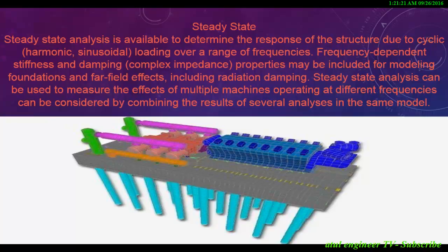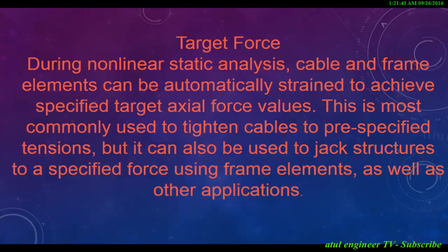Steady state. Steady state analysis is available to determine the response of the structure due to cyclic, harmonic, sinusoidal loading over a range of frequencies. Frequency-dependent stiffness and damping, complex impedance properties may be included for modeling foundations and far-field effects, including radiation damping. The effects of multiple machines operating at different frequencies can be considered by combining the results of several analyses in the same model.